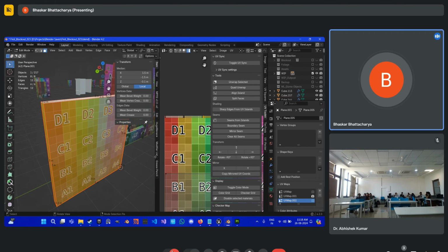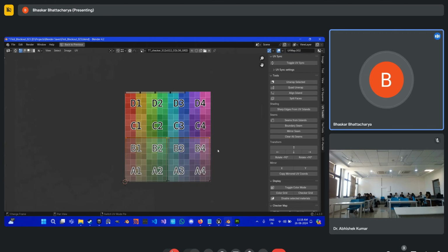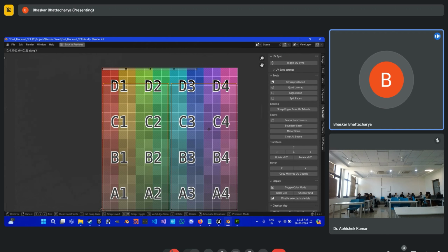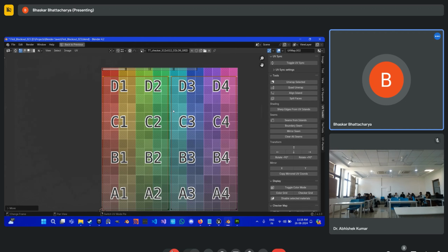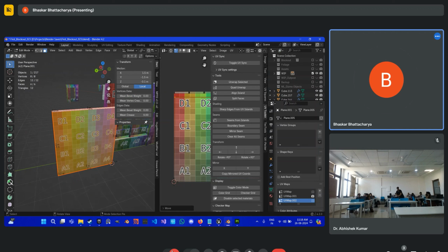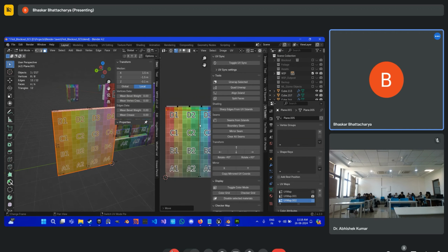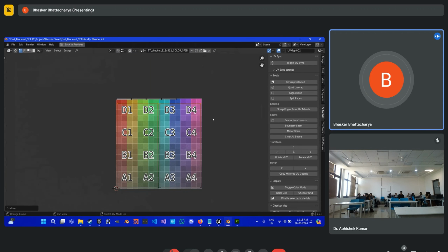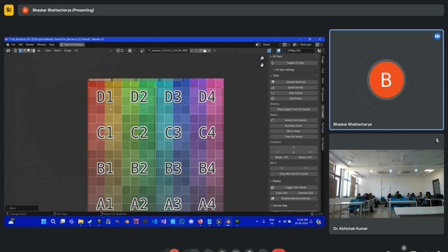And then what I'm going to do is take all these major faces, and again this may look weird because for regular UVs we do not usually do this, but like I said, for light map UVs we want the maximum resolution possible for most important faces. Okay, so I stretch these faces so that they occupy the most space.